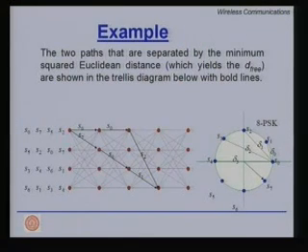Let us look at an example of a TCM. Here we have 4 states, but for every state you have 4 branches coming out. Clearly 4 states indicate that 2 bits are present in the memory of the TCM encoder. However, 2 input bits are coming in, contributing to 4 branches coming out of every node.